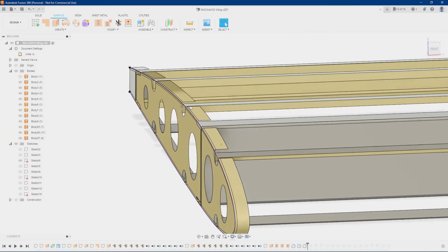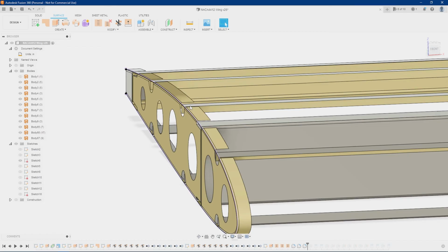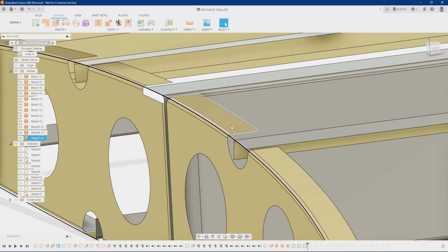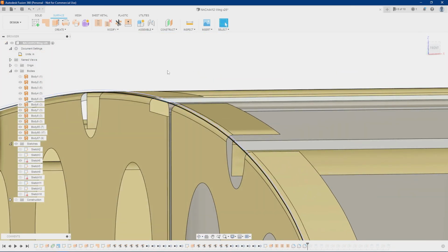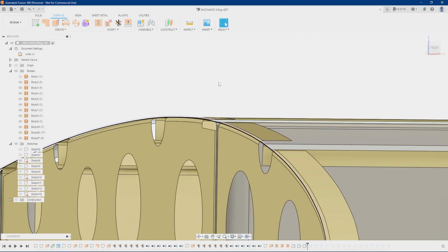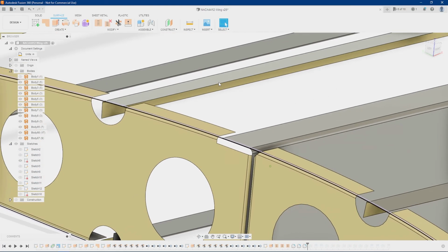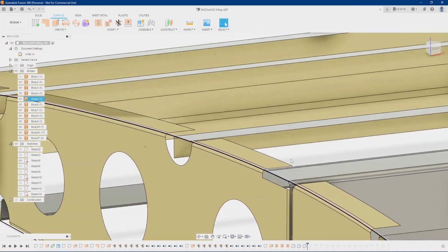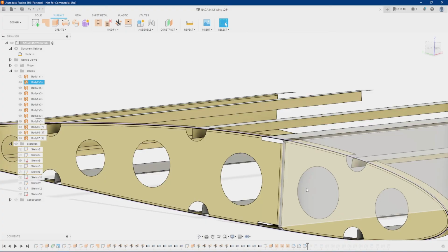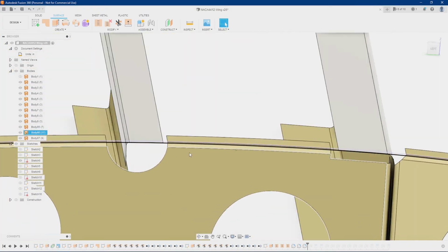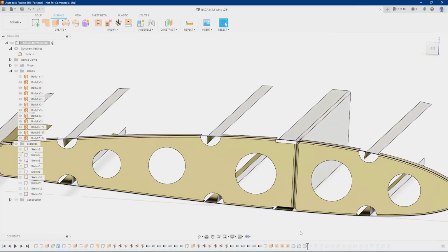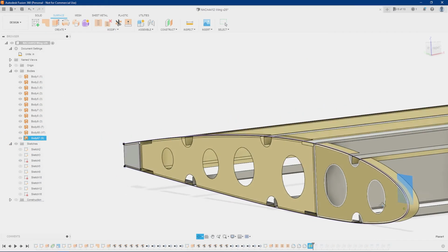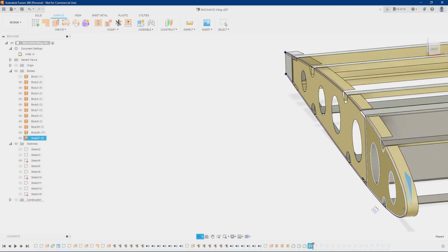And generally for aluminum, it varies on alloy and temper and whatnot, but if you can be between 1 and 2 times the thickness as your bend radius, then you'll be in good shape. So you don't want it to be so crazy tight, because then you can get cracking, and also you might have a bit higher stress with very tight radii. So if you can be a little bit generous with the radii, you'll be in good shape. So that's adding radii to all these edges, so these transitions are nice and smooth. And now I think I start essentially doing a ton of split face operations.